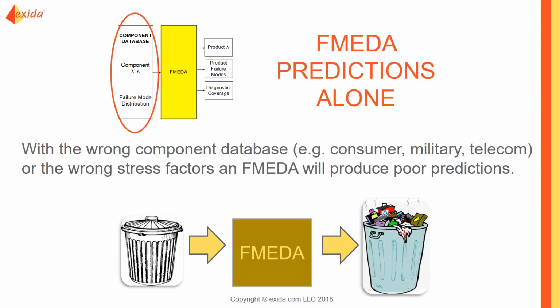You're going to see a lot of optimistic certificates, and when you do, you need to start asking questions, because it's very dangerous. There are now websites out there that will show you what an acceptable range is. As long as the product falls within that range, you can give it a thumbs up and move forward. Even if you don't know anything about functional safety, if it falls within that range, you're good to go. There's a website, I can send it later, called silsafedata.com. You can go on there and get the ranges, so you can see what a typical butterfly valve would be.